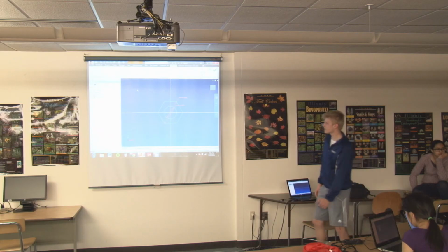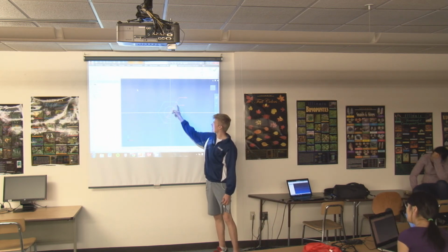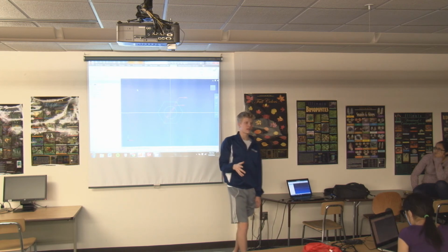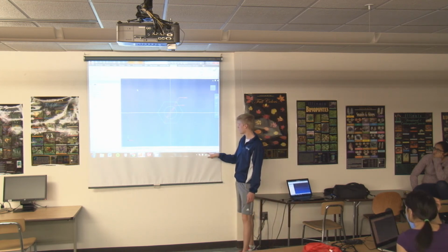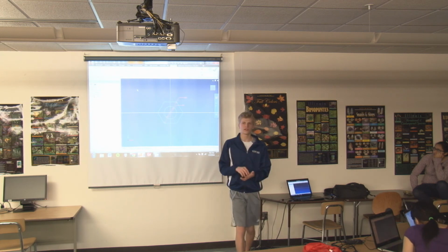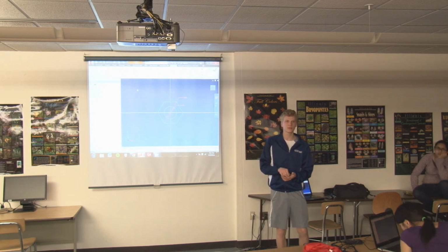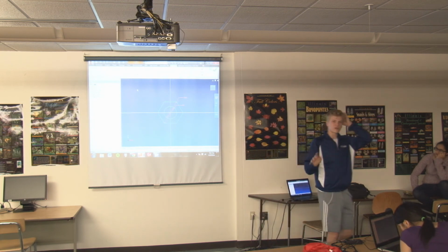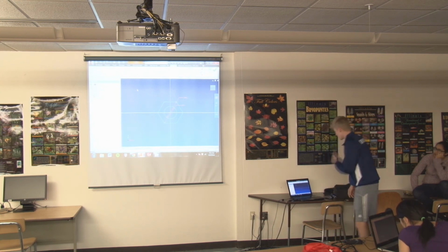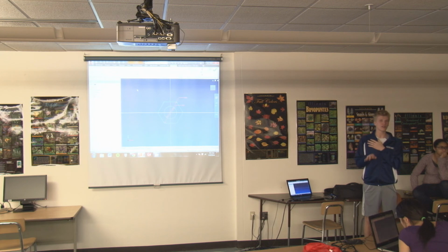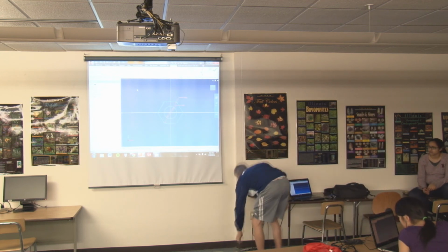So now you can see on my CAD, all of these lines are now green. For yours, they will probably be a darker blue. And you can look down in here. It says fully constrained. That means every element in the sketch is now fixed in its position because you set these different constraints on it, so that they can't move or change dimensions. And that's good. The idea is you want to have all of your sketches have that fully constrained tool underneath.